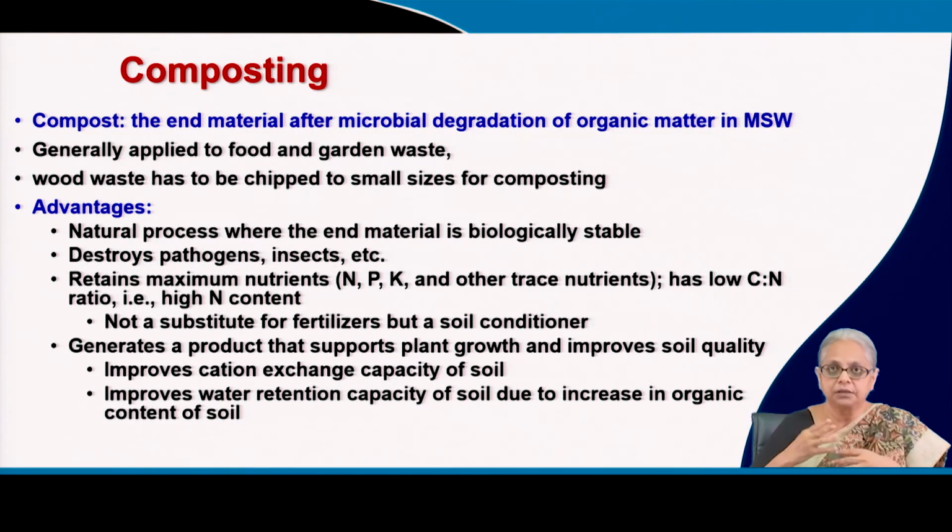You are providing recycling of the important nutrients, so nitrogen, potassium, phosphorus, all of which are very important from an agricultural productivity point of view, can be recycled easily using this process. It also helps to destroy pathogenic organisms, insects, and larvae; all these can be destroyed quite easily in the composting process. No significant effort is required in many cases if you do it right.